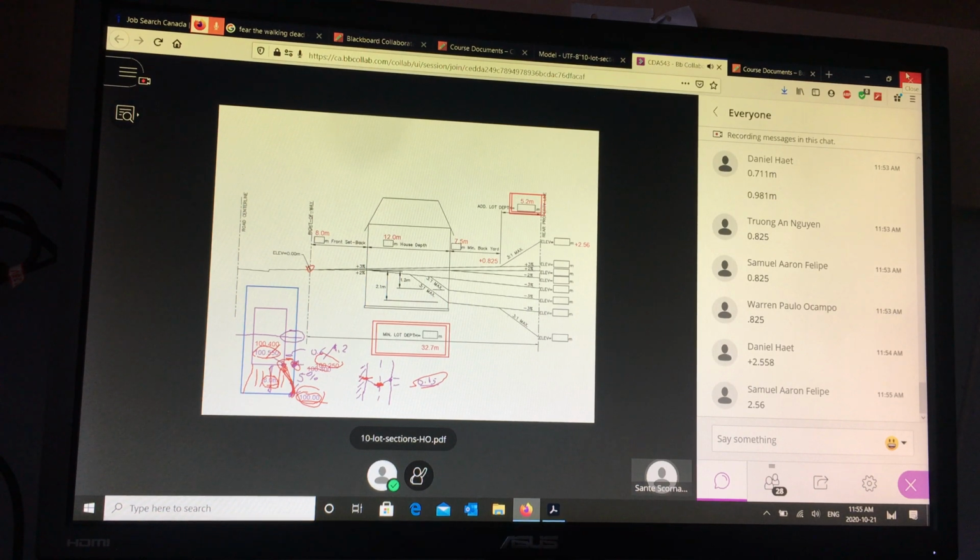So imagine the difference. You know the drawing you're preparing for Friday? If you have an elevation at the front, and you have an elevation at the back, say your existing ground is up here somewhere, then the way you're going to design it is you're going to go from the front to this point here, up at 3%. Then from there, you're going to go to the back, up 3-to-1. And then to make up the difference, that's as high as you can go before you need to put in a wall. You're going to need a wall here to get up to the existing ground. If the existing ground at the back is higher than 2.56 than the front, this is the best you can do. And if you use that 3-to-1, you minimize the height of the wall, right?